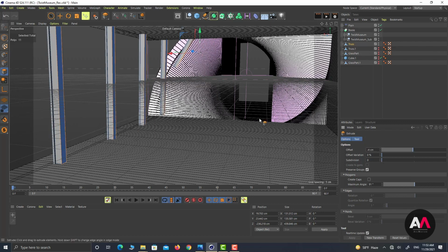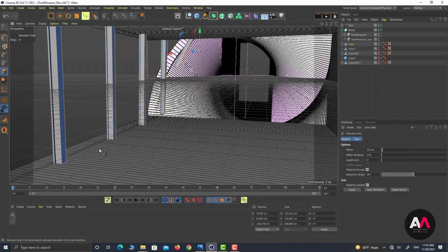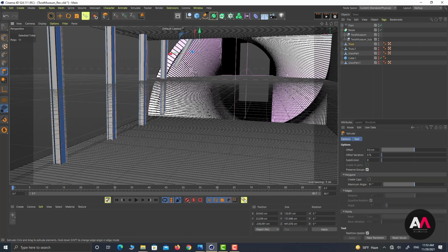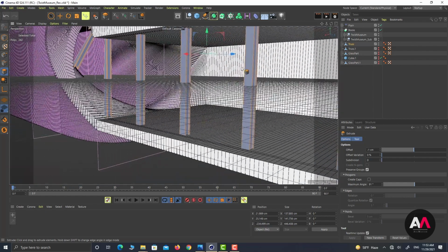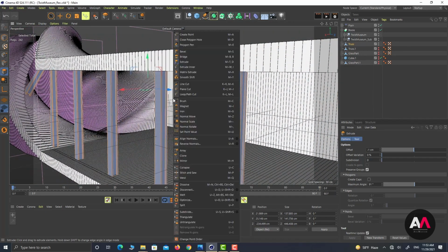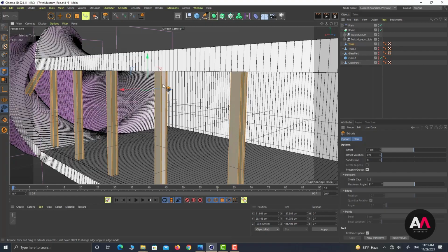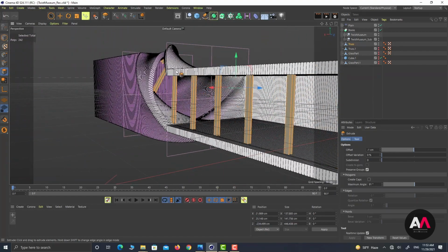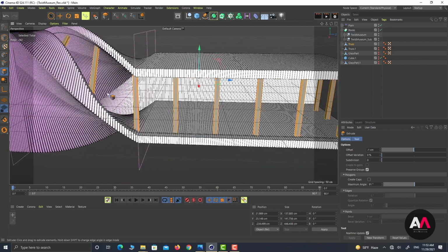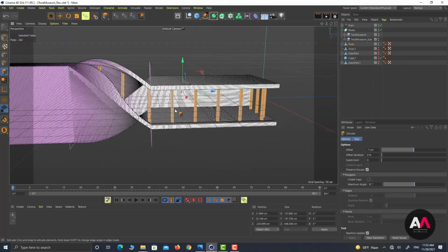-4 is a good value again, and again inner extrude, extrude it outward this time, -9, and extrude outward again, the value -1. And I select all of them because the normals are turned inside. I can just come here and reverse normals. So here are our horizontal, our vertical structure of the truss, and now we need to add the diagonals.